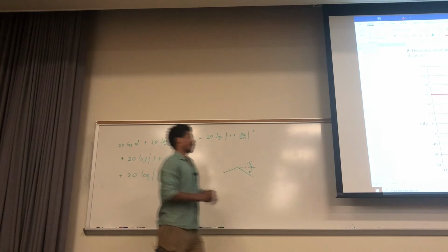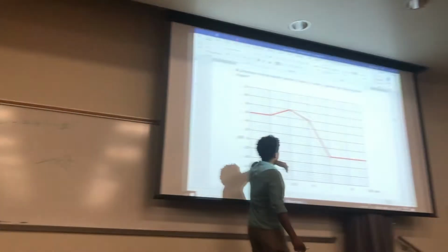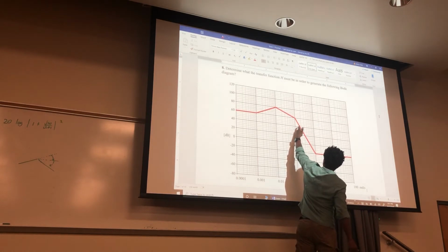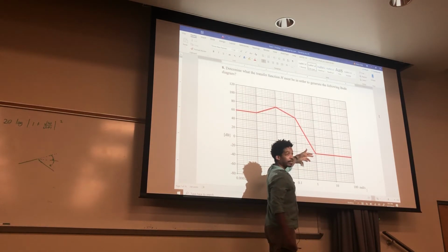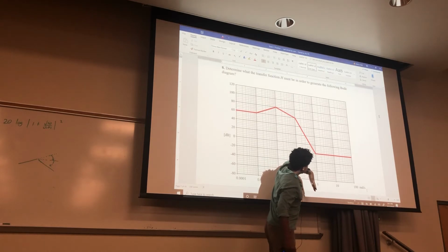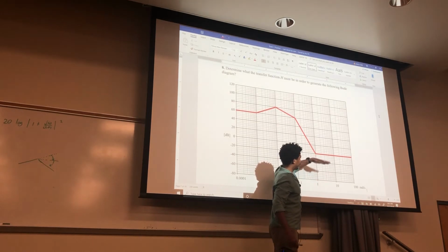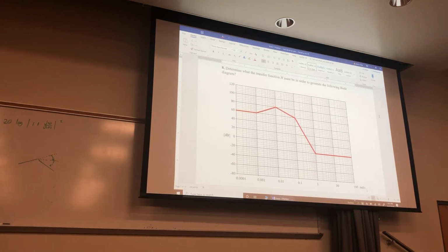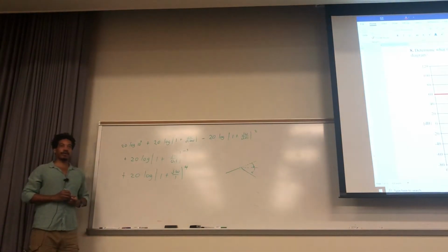And so we've got to go back up the other direction. So how many decibels per decade is this? This is like 40 decibels per decade. So we have to eliminate all that as we back up, 40 decibels per decade. So it's going to be 4.